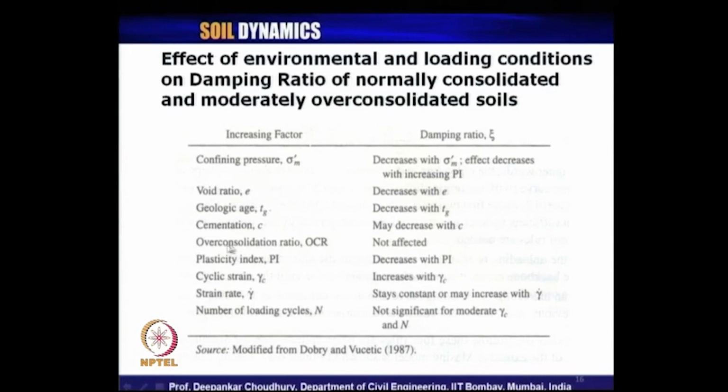What is the effect of over consolidation ratio? It was observed by Dobry and Vucetic in 1987 that OCR is hardly having any effect on the values of damping ratio. So, for different OCR values of soil, we can expect the damping ratio to remain almost the same. What is the effect of plasticity index?